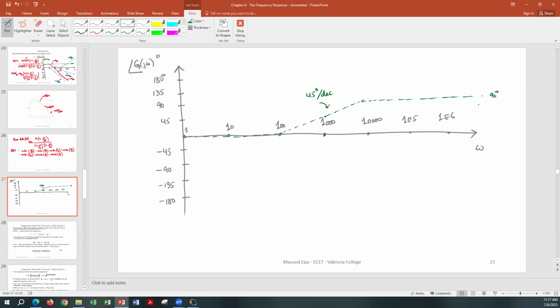That's for the 0. Now we have 3 poles. Make sense? Yeah. So for the phase Bode plot, the rule that we are using, the one we discussed, is until 1/10 of your frequency, we assume that omega over omega naught is very small, approximately 0. So tangent inverse of 0 is 0.